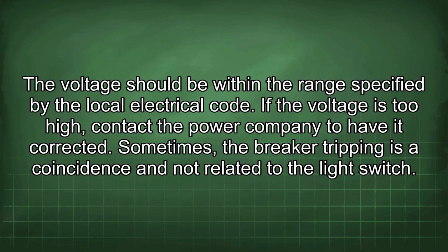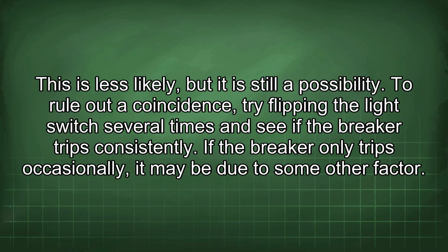Sometimes, the breaker tripping is a coincidence and not related to the light switch. This is less likely, but it is still a possibility. To rule out a coincidence, try flipping the light switch several times and see if the breaker trips consistently. If the breaker only trips occasionally, it may be due to some other factor.